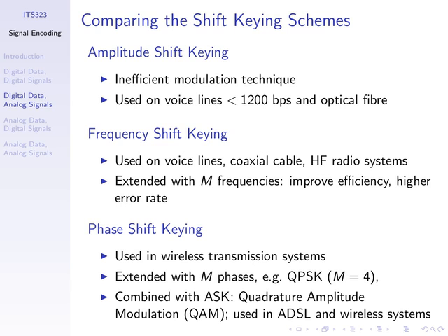We can extend them to include multiple levels. In the previous diagram, we just had two different levels. One amplitude or another, one frequency or another. We could have 4 different levels, 4 different frequencies. Each frequency represents 2 bits. The same concept as when we had our digital signalling where we had 4 levels, each level representing 2 bits.